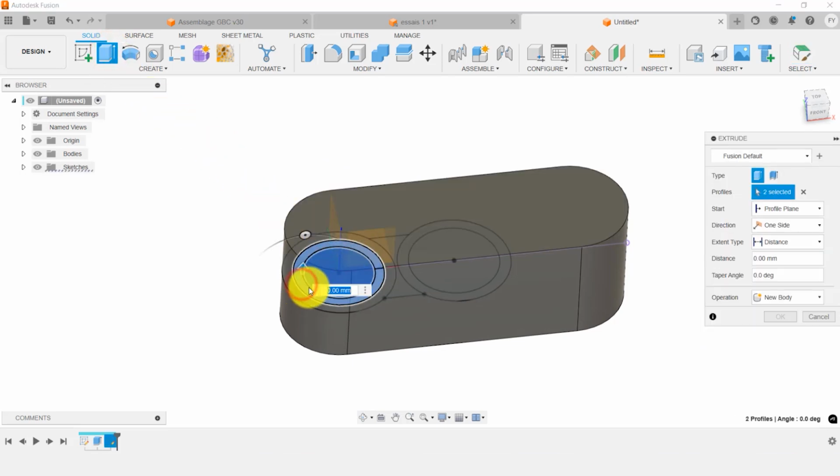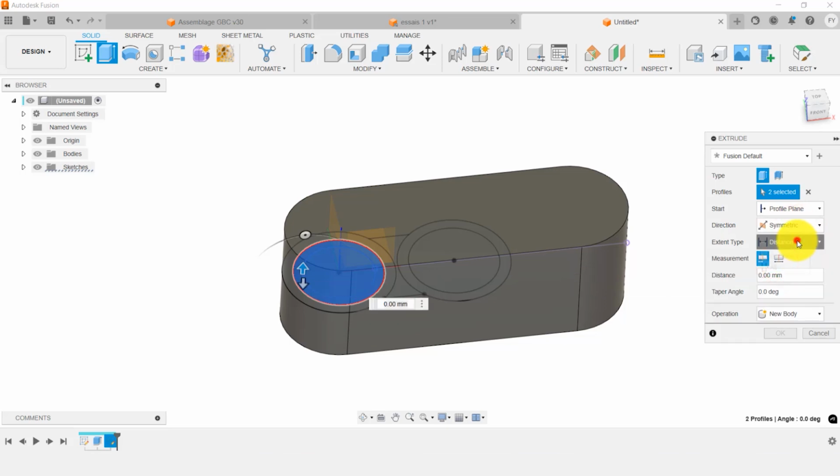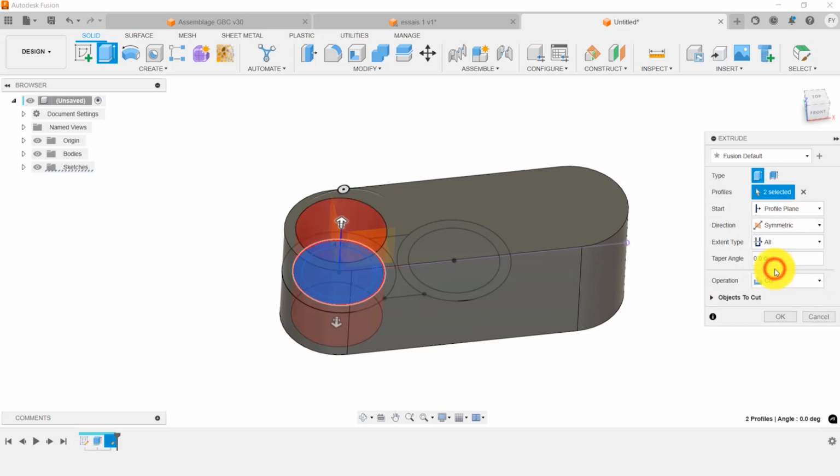Define a symmetric extrusion through the entire part. And here we see that since the extrusion starts from an already created volume, it defaults to removing material. What I could have done is join the material or suggested other functions, but cutting is exactly what I want, so it's what is proposed by default. This is perfect. I have now removed the material.